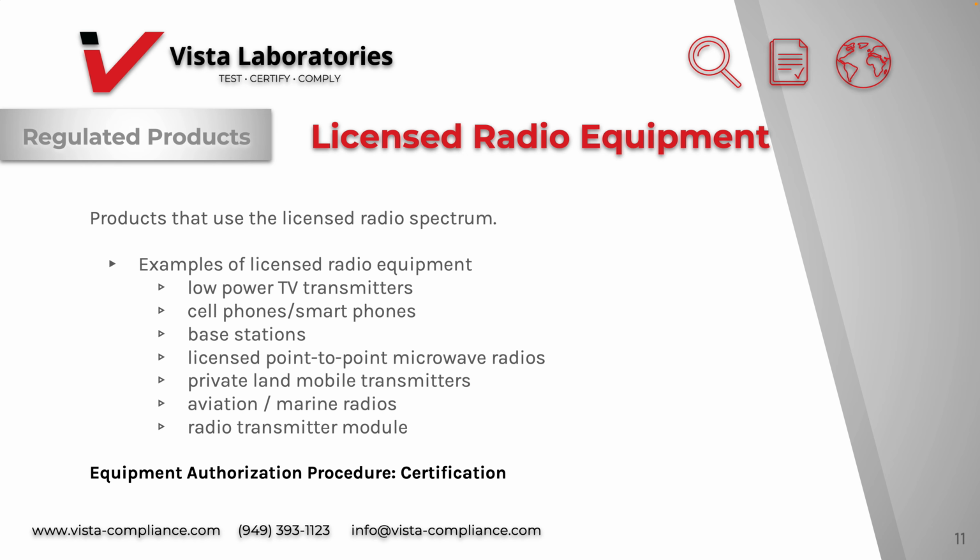For equipment operating in licensed radio services, these products are the ones that use the licensed radio spectrum. This can range from fixed microwave links to cellular telephones to mobile broadband services and are considered radio frequency devices that are subject to equipment authorization. Some rule parts for licensed radio equipment are 47 CFR Part 96 for Citizens Band Radio Services, CBRS. For broadband radio services, BRS, that falls under Part 27. Part 22 is for cellular services, and Part 20 and 90 are for signal boosters.